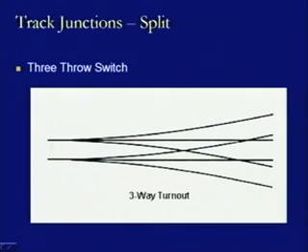What we can see is that this is a main track, this one, and then this is getting split into 2 more tracks which are going in either direction, that is it is going in this direction or it is going in this direction, again symmetrical in nature. Then this is known as a symmetrical 3 throw switch with the contrary flexures, because this is this way, this is the other side.